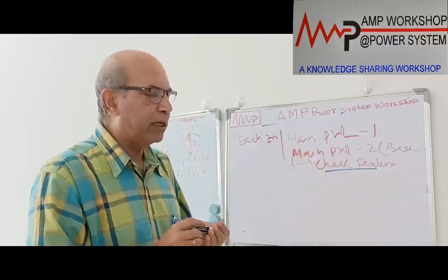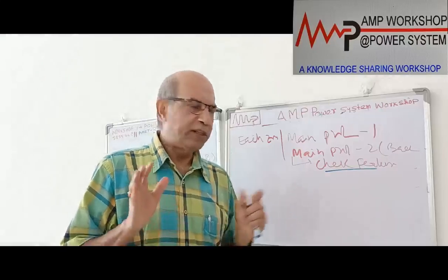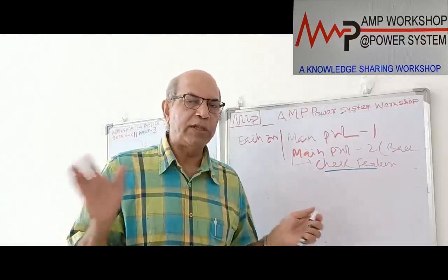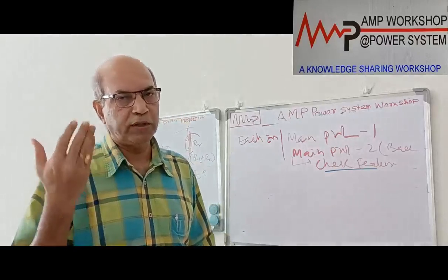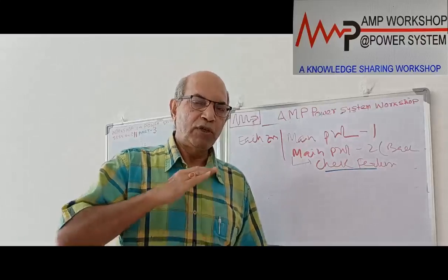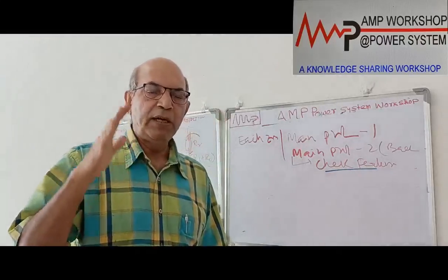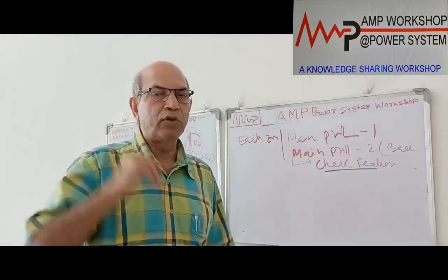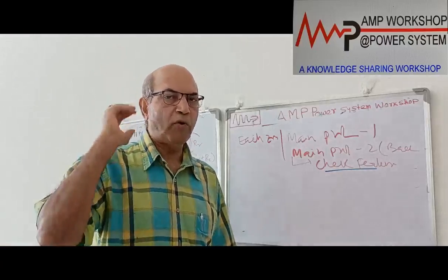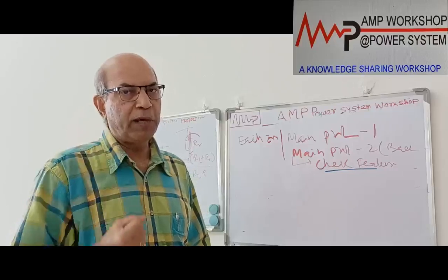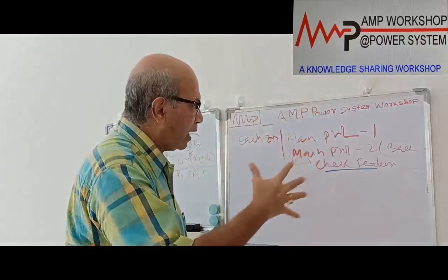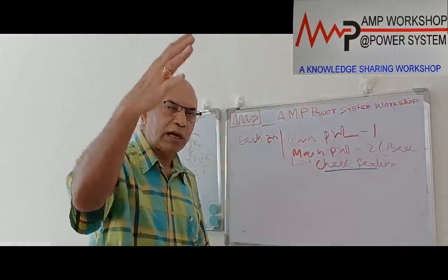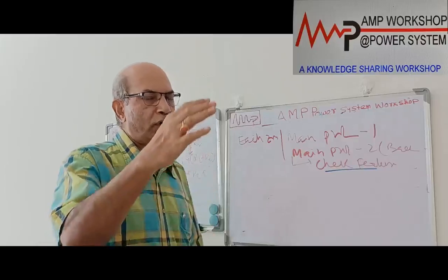Third arrangement: in case of indoor switchgear, this is fine because CT wiring will be limited within the panel. But when the switchyard is an outdoor switchyard, such as 66 kV, 132 kV, 220 kV, where the CT, PT, breaker, everything is mounted outdoor, a bunch of wires will be coming. CT wires will be coming from all the CTs located in the outdoor switchyard. So we do not wire all the CTs directly to the protection panel in that way.